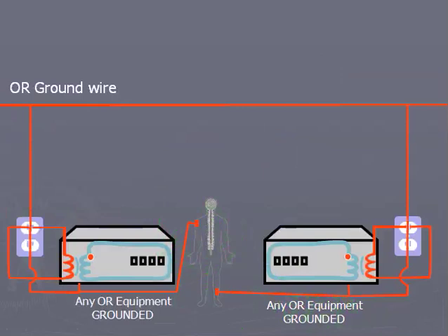Remember that the ground wires from all of the outlets in the building are connected together? Well, there is a thick wire connected between the two different ground outlets illustrated here. For the illustration, let's assume that in the next room there is a heavy piece of equipment, such as a laboratory high-power heating oven or some heavy motor operating, that has a large amount of leakage current running through the ground wire, illustrated here.